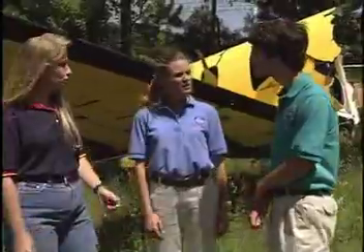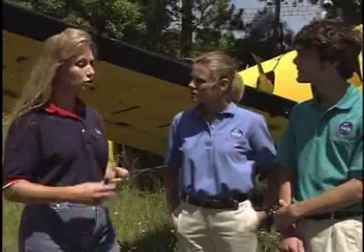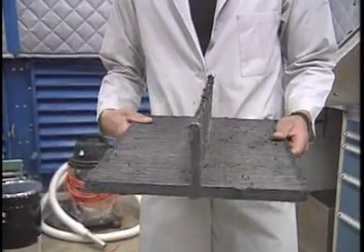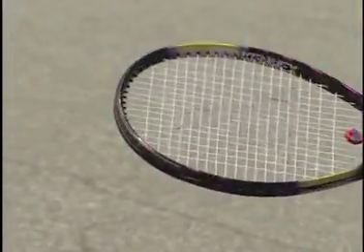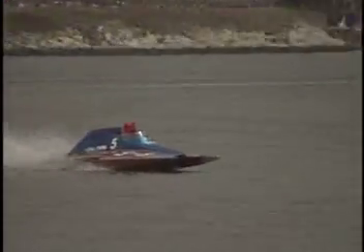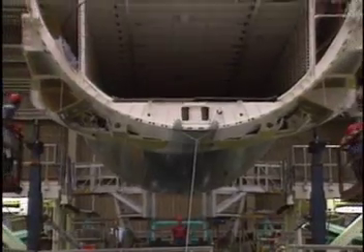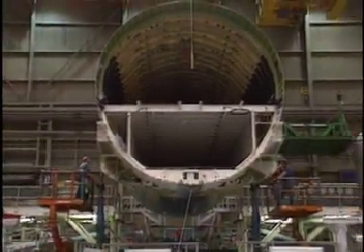Good question. We use human tolerance data and crash test dummy data to develop better energy absorbing designs. You see, aircraft are made of different materials. Some are made of metals like aluminum, and some are made of composite materials like graphite or fiberglass. A tennis racket is a good example of a graphite material, and most small boats are made of fiberglass. Metals and composites perform very differently in a crash, so we have to design the parts to complement the materials the aircraft is made of. Basically, we would not design a subfloor in a composite aircraft the same way we would design a subfloor in a metal aircraft. Can you really design a subfloor that absorbs energy?